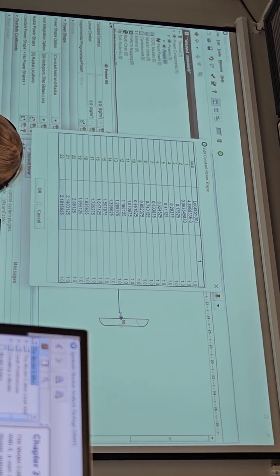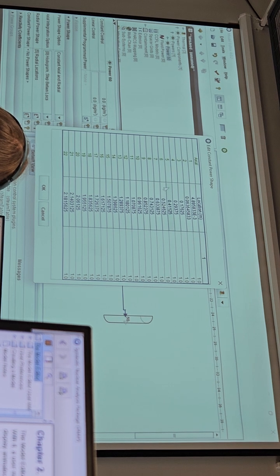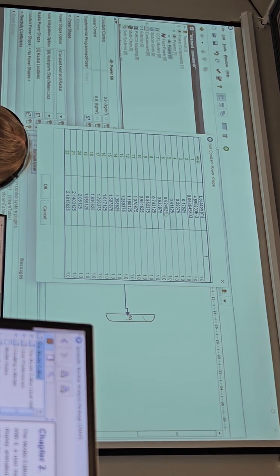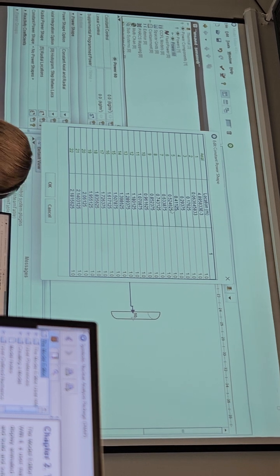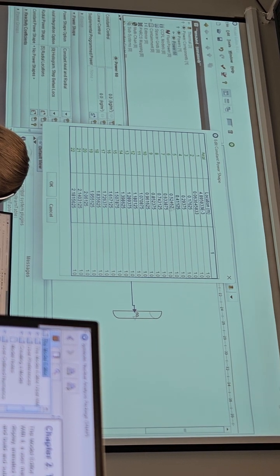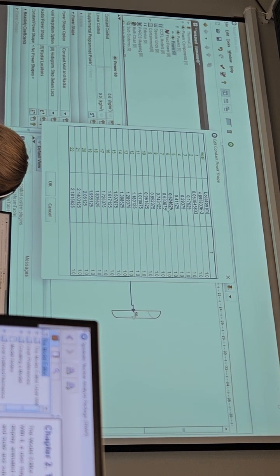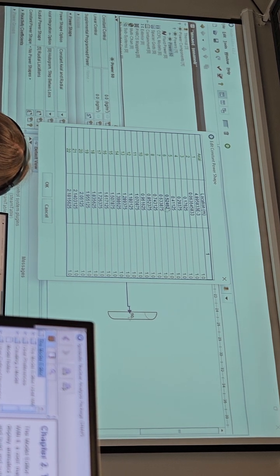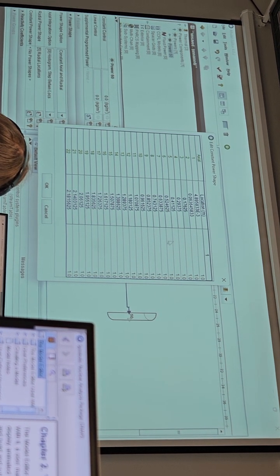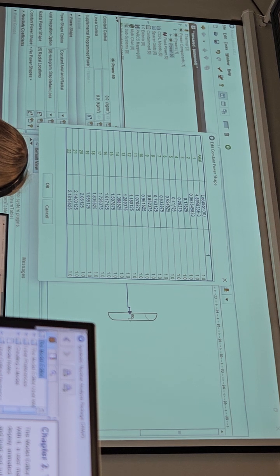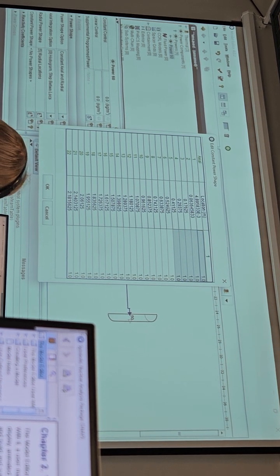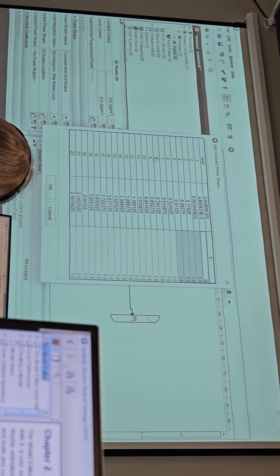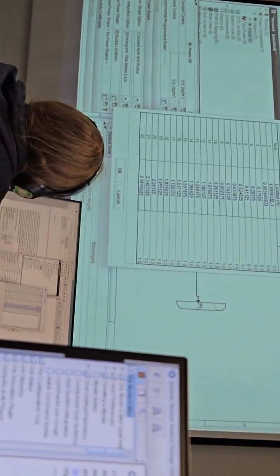So since, for example, here 0.41125 meters, since it is a middle point of the cell, we can assume that the next cell is already heated, because the first 470 millimeters are unheated surface. So then we can define an unheated surface for the first 5 axial cells. And we can just define it as 0. It is an unheated surface.